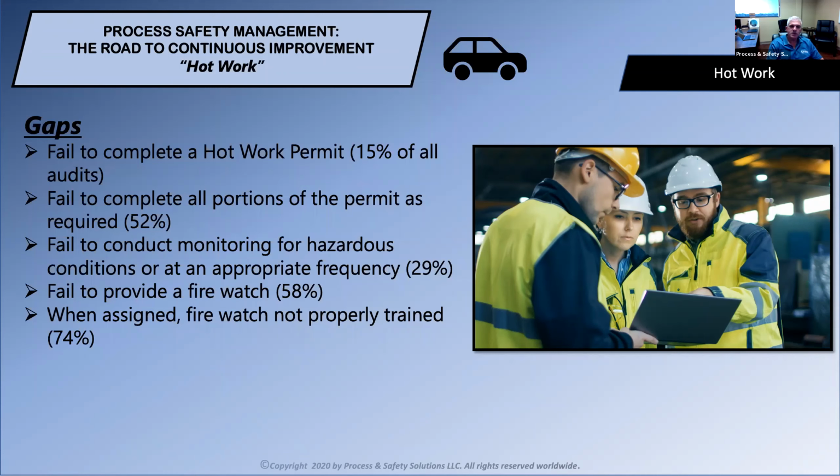The other thing, and this is 74% of the time, so this is a fairly high number: nearly three-quarters of the time when a Firewatch is assigned, that Firewatch is not properly trained. And we're going to go into some of the detail of what we look at when we're looking for Firewatch training. Just because they know how to operate a fire extinguisher doesn't mean they're properly trained as a Firewatch. And we'll get into some of those details here in just a second.